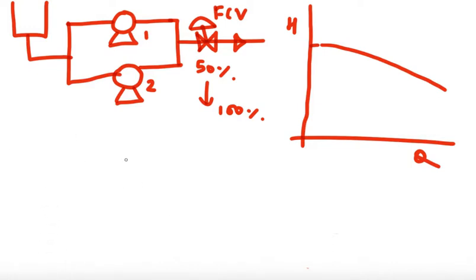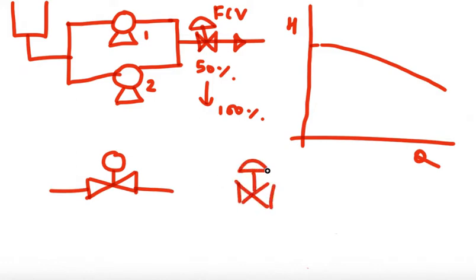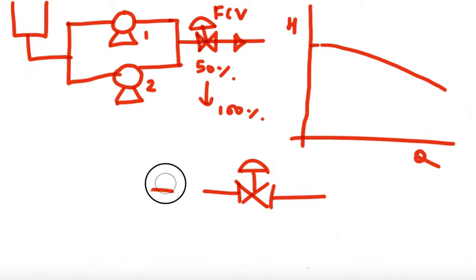I would like to tell you what is the work of a process design engineer for FCV sizing actually. Say FCV is a kind of control valve, right? We can draw it like this also. We can draw in many ways actually. We can draw like this also, and we can put a cap like this. So this is better. So this is my control valve. You know the characteristic of a control valve is defined by its CV value.